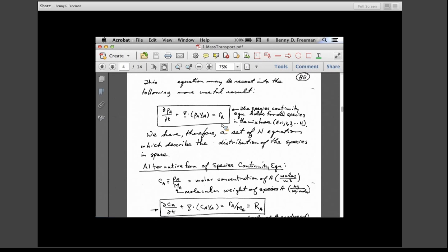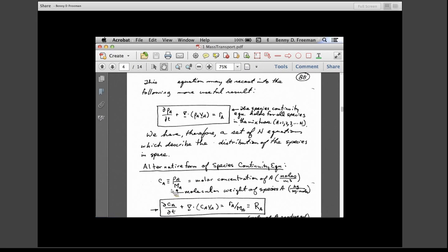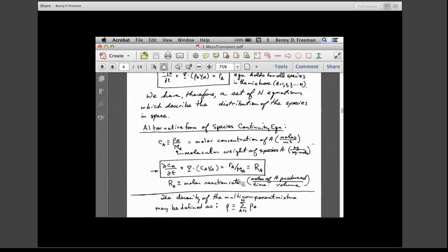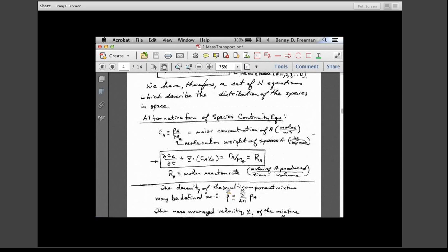We derived this initially in terms of mass concentrations and then used the relationship between molar and mass concentrations to derive an entirely analogous expression in terms of molar concentrations. And these two expressions in the boxes will be the backbone of our mass balance solutions going forward. And so we'll use these quite a bit as the starting point for our analyses of different problems.